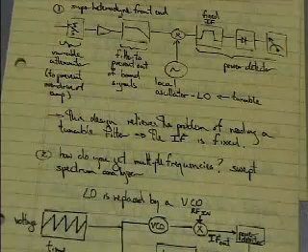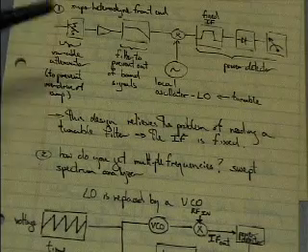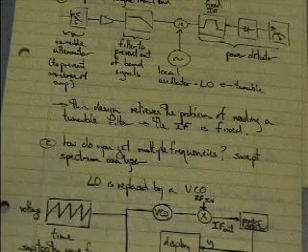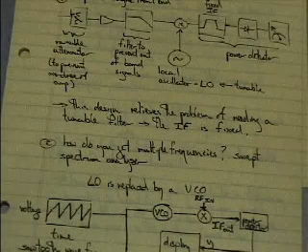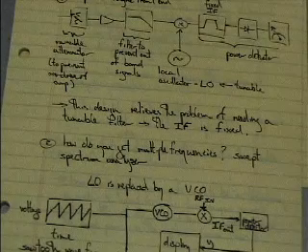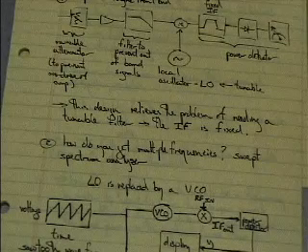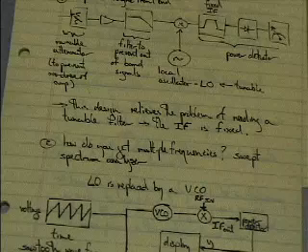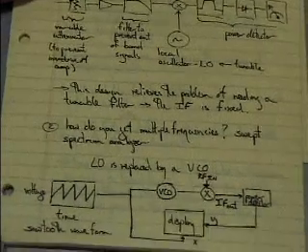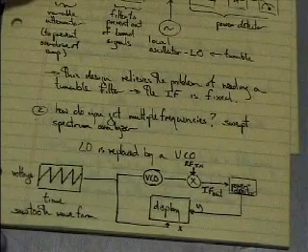All right, like I was mentioning, we'd like to look at the power per frequency over a particular range. For example, the FM radio band. We might want to set up between 88 megahertz and 108 megahertz, and basically look at what the spectrum is, and look at all the signals in there and measure the power of each particular signal. Okay. Well, it sounds like what we need to do is basically sweep over a range of frequencies, and that's exactly how a spectrum analyzer is set up, and this is what we'll be dealing with in our lab.